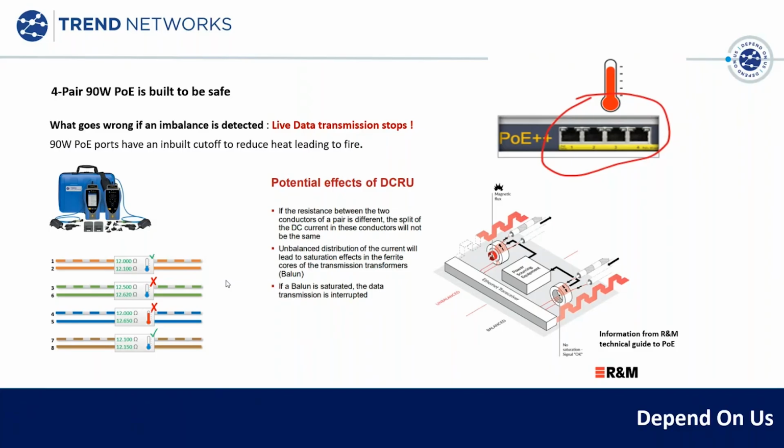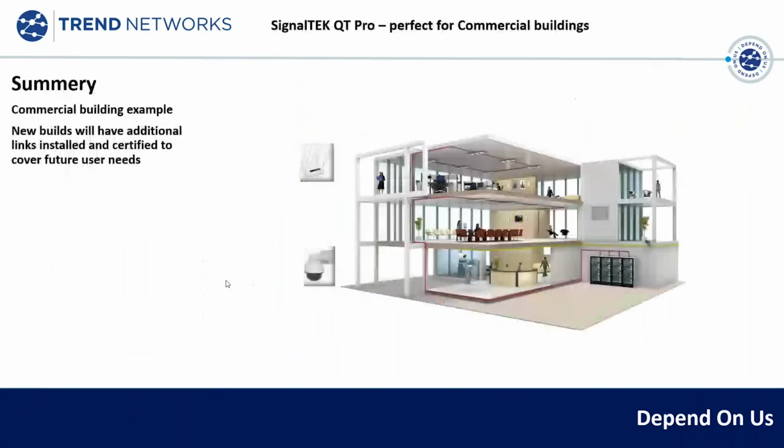So once again, certification is still important for the fundamental parts of the first fit in the installation of the network. So let's share where we are now. We're just wrapping up now. Summary is that live or a building or infrastructure typically has a fiber backbone as we connect buildings, and they install spare cores. So you imagine we've got to allow for expansion, because it's very, very difficult when we first install all this mass of cable into a building. At the first point, we allow for expansions.